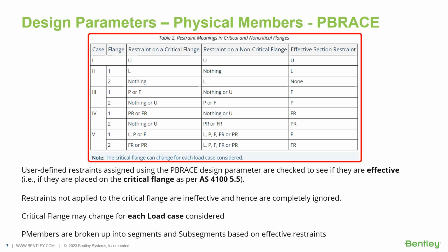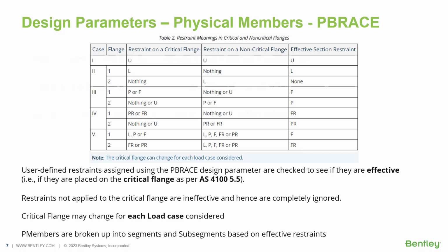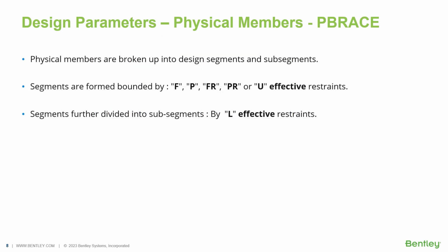Based on the restraints that are determined to be effective, physical members are broken up into design segments and subsegments. Physical members are divided into segments by any effective restraint other than the lateral restraint. The segments thus created are then divided into subsegments by the lateral restraints.